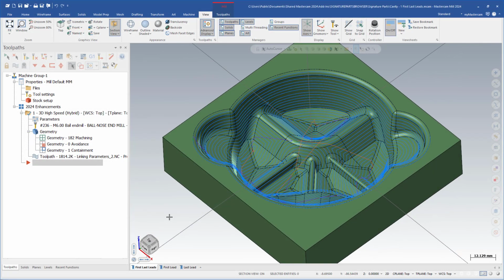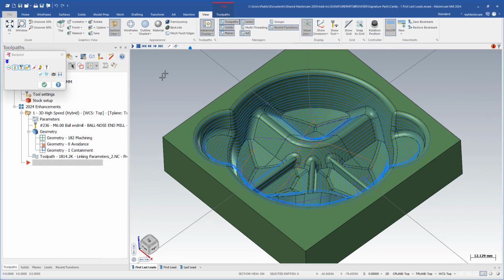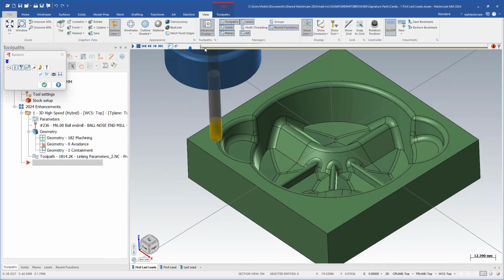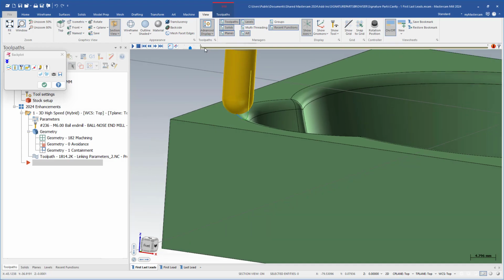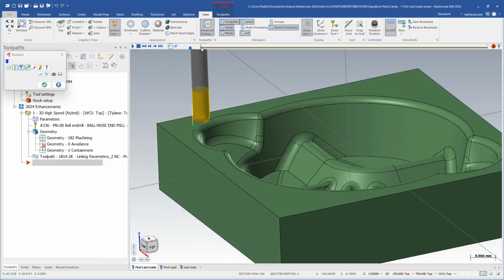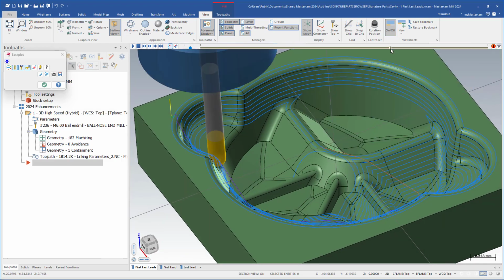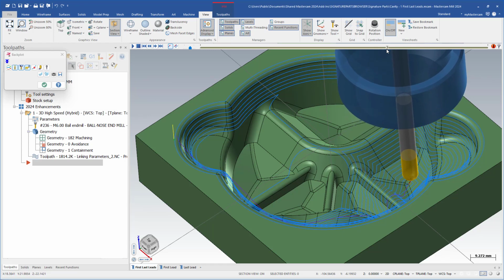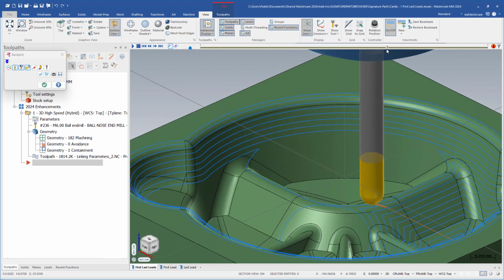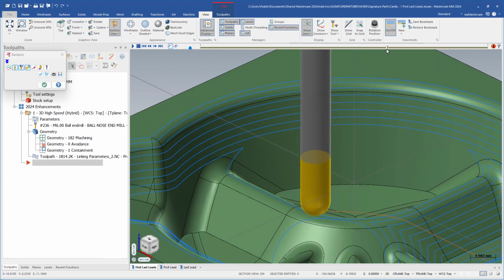And here, if we take a look at our toolpath, the first place that we're going to come in on this toolpath has us coming in with this vertical arc, which is okay. I'd kind of prefer a horizontal one for something like this. And then it's going to continue to move around. It's going to break up the toolpath in a few places. Notice that as I move from this pocket here, and we move up, so we're almost there. We move up, and we're going to move into this next one.